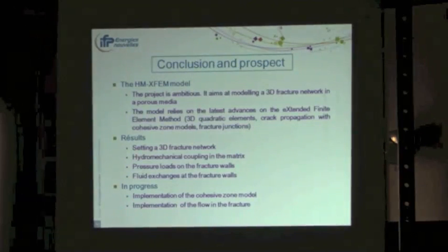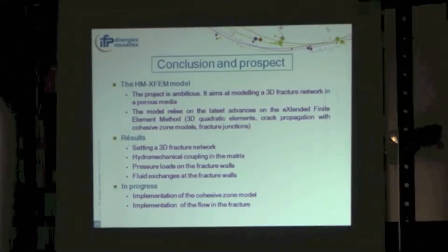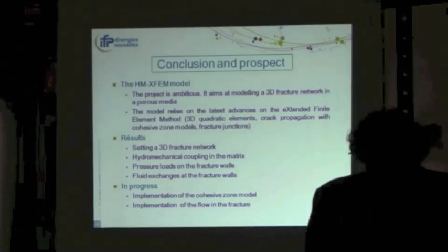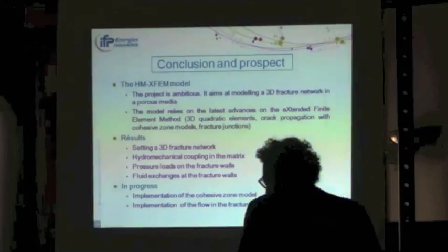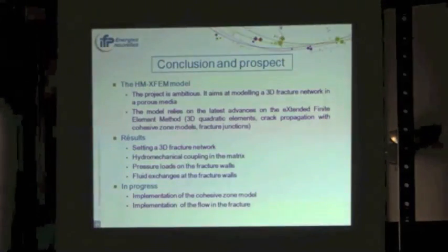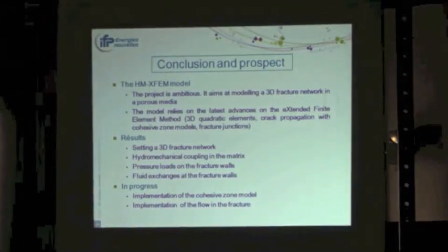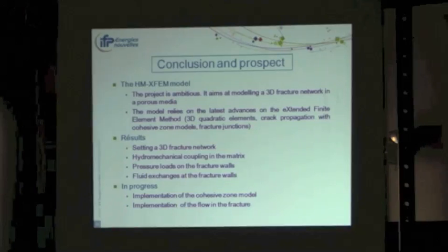Now to conclude, the HM-XFEM model is very ambitious. These are very heavy elements. It requires a lot of developments. In terms of modeling a 3D fracture network, it relies on the latest advances in the extended finite element method. I'm talking about 3D quadratic elements, crack propagation with cohesive zone models, and fracture junctions.